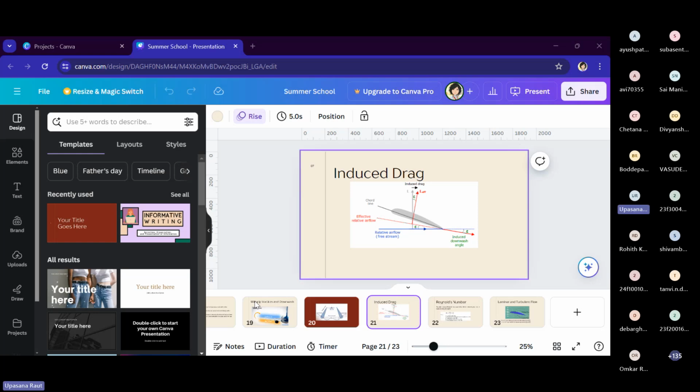See, again, it depends on the inverse of the wingspan, right? So we can increase the wingspan to decrease the induced drag. Yes, not the airfoil, but the wingspan, you can say, the entire wingspan by chord length. So yeah, it also depends on the size of the airfoil.